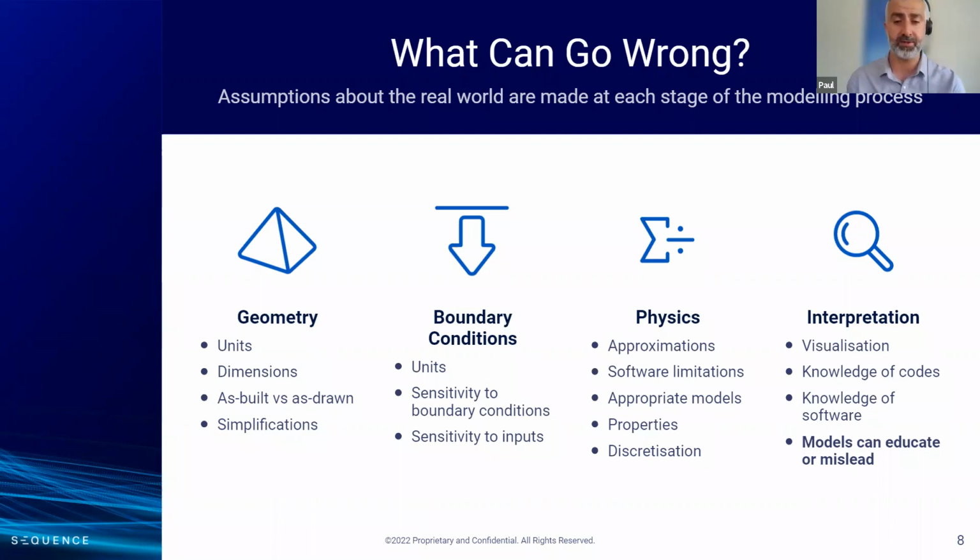And finally, I guess, discretization. That is basically how fine a computational mesh or a finite element mesh you've developed for your model. For those of you who don't know what that is, it basically allows you to break up your domain or whatever it is you're simulating into elements. And the more elements or the more points you have in that model to represent whatever variable of interest you have, the better the result is, generally. But obviously, the amount of computational effort increases exponentially with increased model size. So there's definitely a motivation to use those elements effectively.